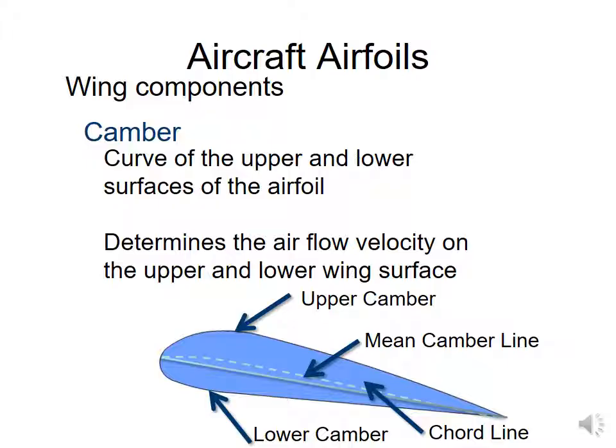According to Bernoulli's law, the increased velocity means a decrease in pressure. A lower pressure above the wing compared to below the wing sucks the wing upward, creating lift. The top wing surface is critical for generating lift. Anything that slows airspeed above the wing will decrease lift. Major sources of velocity reduction are dirt, ice, and surface deformities.